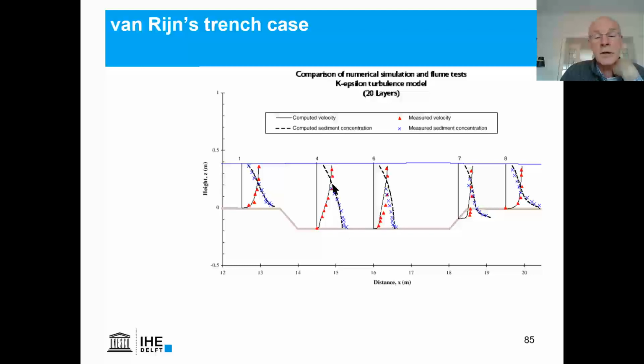You see this again, the model captures this fact very nicely. And here again, there's an accelerated picking up of new sediments as this flow is so concentrated near the bed, until finally the concentration goes back to the usual Rouse profile in a logarithmic velocity profile.